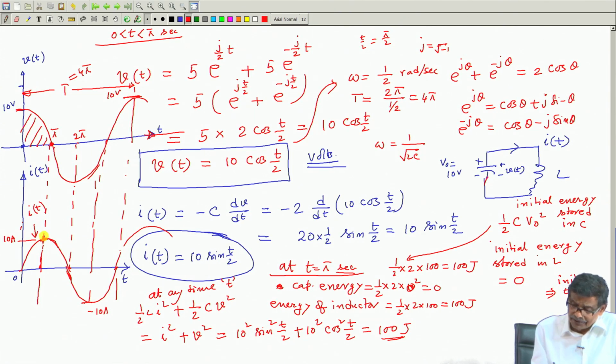Therefore, wherever current rose to 10 ampere, from that it must start decreasing. And during this pi interval, you have applied a negative volt second, and these two are the same. If you integrate this volt second and that volt second, this is the same. That is why current rose to 10 ampere, but once again came to 0 ampere.